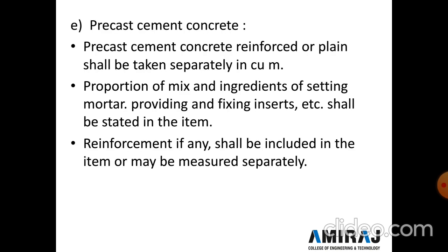Now next is precast concrete work. Precast cement concrete, reinforced or plain, shall be taken separately in cubic meter, and the description shall include mold, finish, hoisting, and setting in position. The proportion of the mix and ingredients of the setting mortar, and providing and fixing the inserts, shall be stated in the item. Reinforcement, if any, shall be included in the item or may be measured separately.